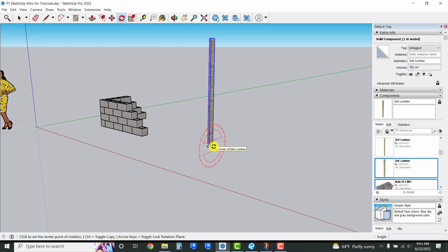So I'm on the bottom right corner right now. I'll click once to select that as my pivot point, and then I'm going to run straight up that compass at a 0 degree to select where I'm going to start the rotate from. Click to say this is where I want to bring the rotate from, and then come on down 90 degrees.